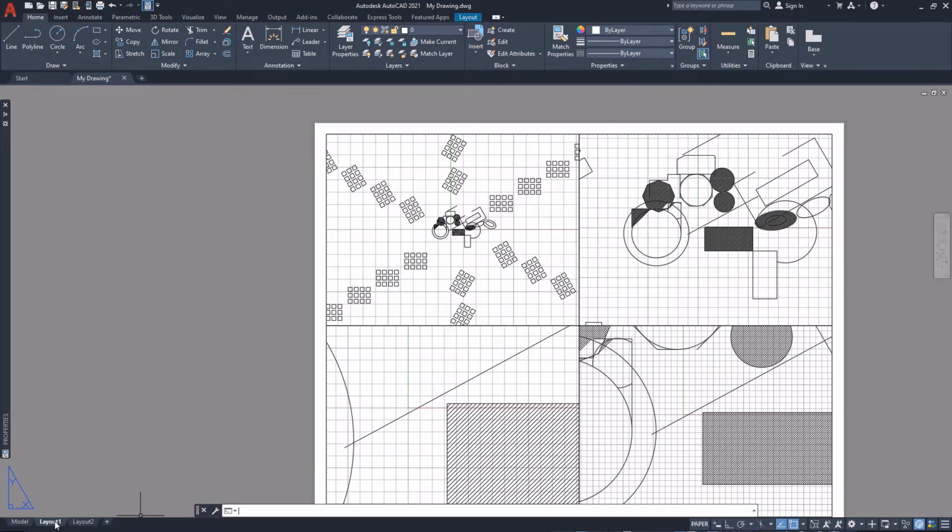A viewport window can be described in several ways. The creation of a viewport window is equivalent to cutting a hole or window in our drawing paper, and through this hole or window we can see the objects and annotations we have created in model space. It is the drawing scale factor that the user assigns to this viewport window that allows the annotative scaling mechanism to properly adjust and resize visually any annotative objects that are displayed.